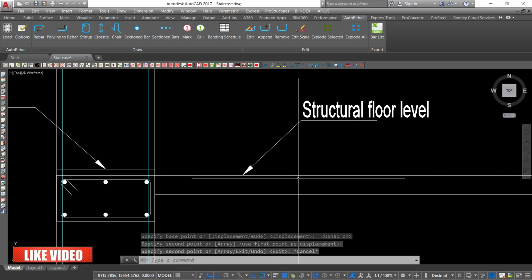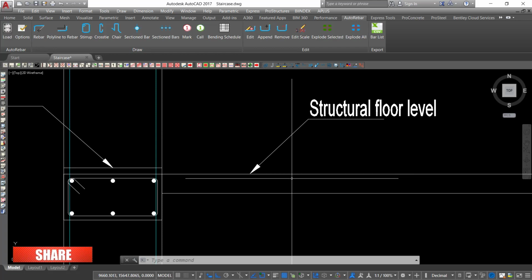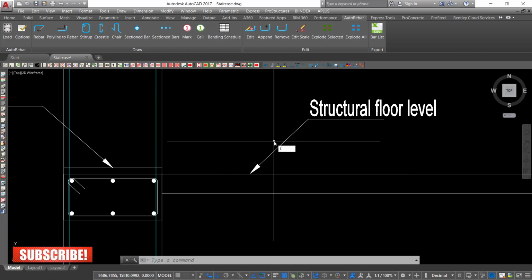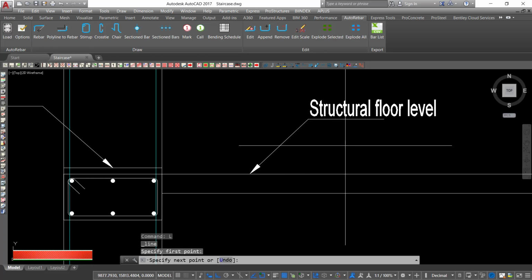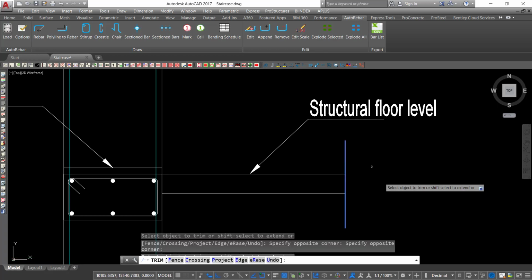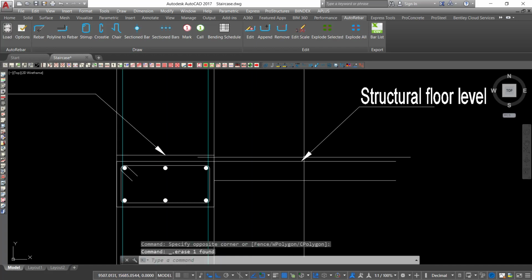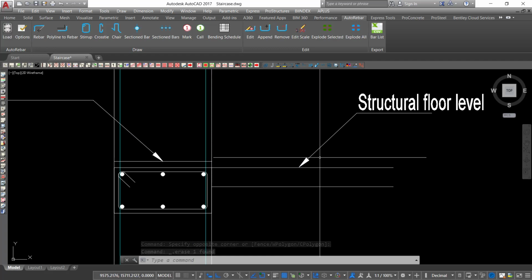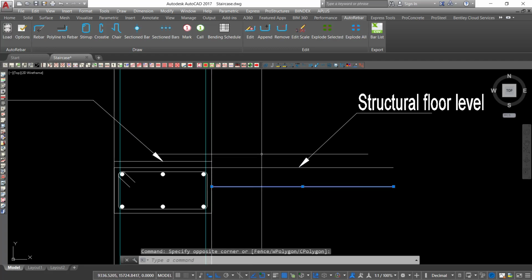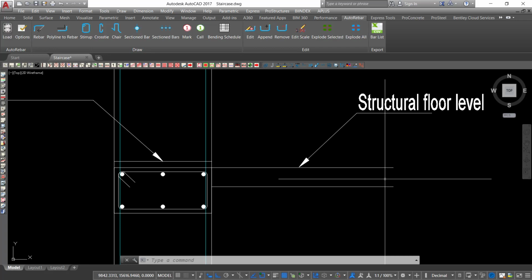All the instructions will be given on the leader. Now, once we have this, and this can be always trimmed off, just type L and cut off this, and type TR and select on that and trim that, so that we don't have so many huge lines that scares the newcomers on detailing. Now, I've selected on this. Now, what I want to do, I want first of all to close, or I don't need to close anything. I'll just close that one. I'm at the final stage.